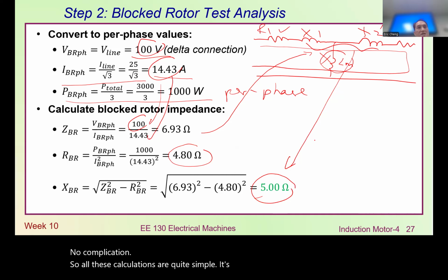So this example, again, has a three-phase motor. We have a 6-pole, 415 volt, 50 Hz, star connection. Now this motor is star connected, not delta. So you can see the correlation between them. And then you have the following parameters. In the block rotor test, the full voltage is 415 volt, but now we're only using a much lower voltage for safety. So you can see that it must be low voltage. And then current, we measure 35 amp, the power is 4.2 kW, and the frequency we're using is 50 Hertz.